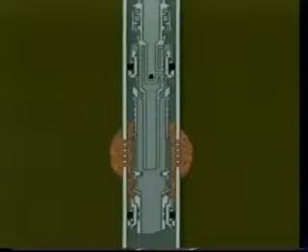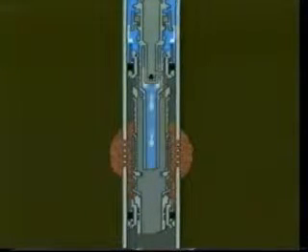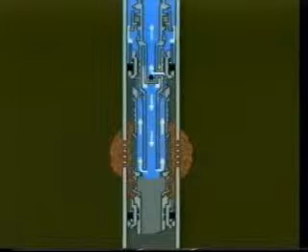Fluids circulated down the annulus enter the bypass ports above the packer, flow down the wash pipe, and then up between the wash pipe and screen and into the gravel pack port. This reverses out any excess gravel from the work string and cleans any debris from inside the screen.